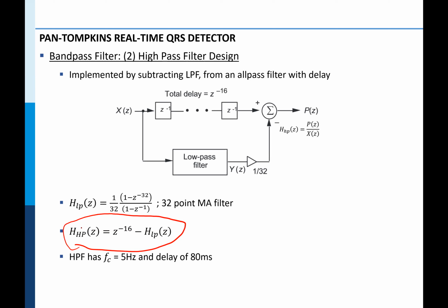So essentially, that translates into a block diagram representation like what's shown there. So the filter transfer function for the high-pass filter that is used in the first stage of the Pan-Tompkins is this notation, and the low-pass filter's transfer function is given here. Okay? And the low-pass filter, just like how we saw before, would be seen as a moving average operation.